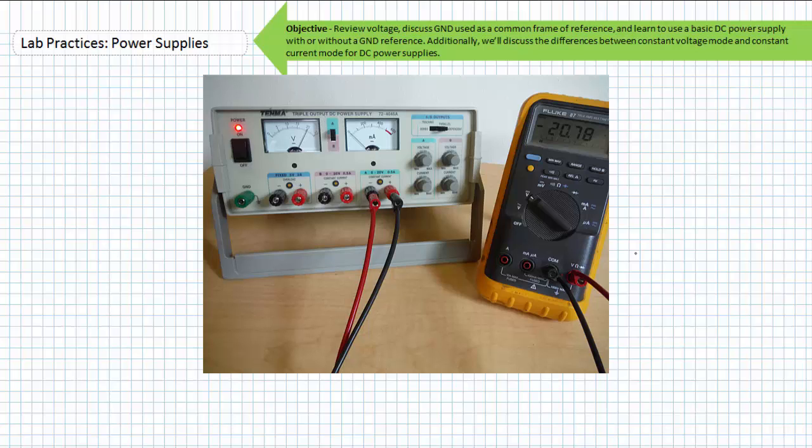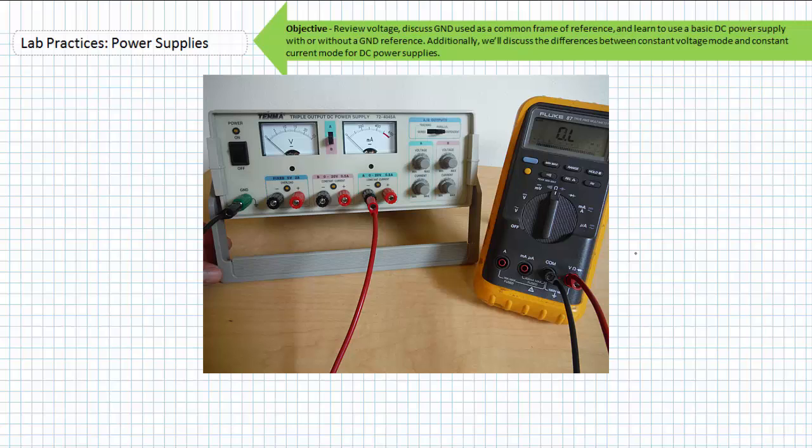Let's start including a ground reference, but before doing so, let's turn off our power supply and do a continuity check with our DMM in ohm meter mode. Again, the power supply is off, and I would never ever do a continuity check with the power on. Is the ground lead in any way, shape, or form connected to any other lead? The answer is no. Any combination of terminals with the ground connection indicates an open circuit.